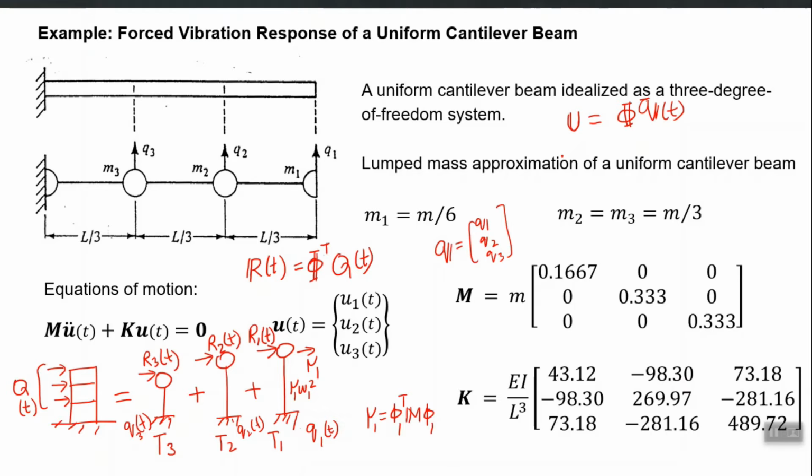So this is an overview of modal response history analysis. No matter how complex the structure is, you can always mathematically decompose it into a sum of many SDF systems. Theoretically, the number of those single degree of freedom systems is equal to the number of modes or the number of degrees of freedom. But the simplicity involved in this method is that you don't need to consider all the modes and combine all modal SDF systems to get a response which is accurate enough. You only need to combine the first few modes.